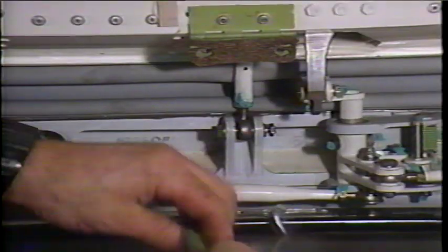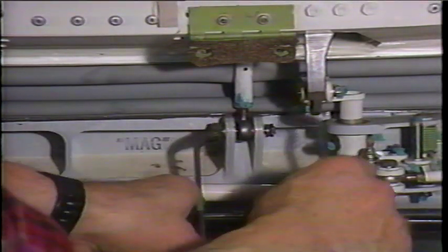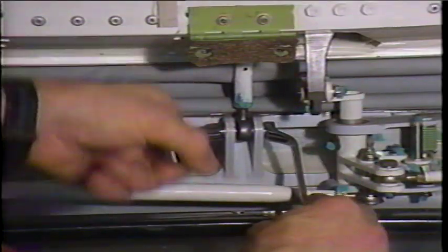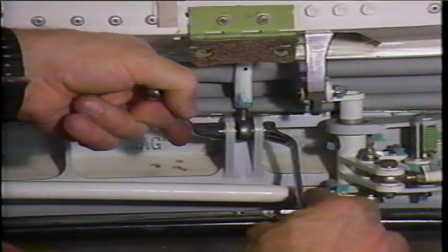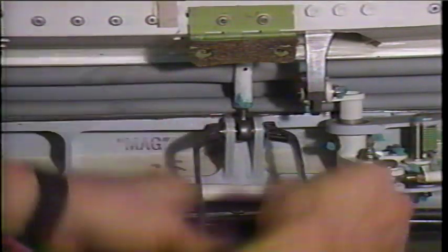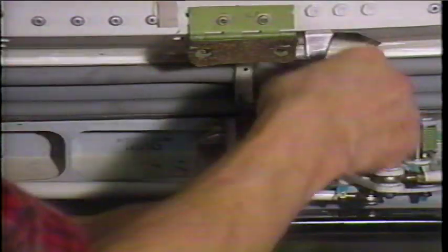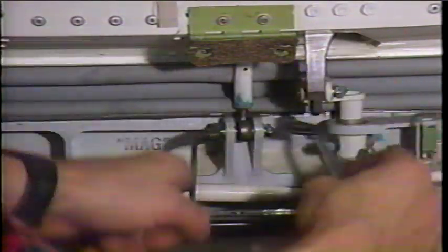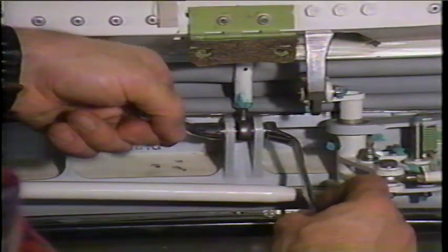The gate is in the proper position when the shim cannot be pulled out. Adjust the gate push rod as required in 1/2 turn increments. Install the bolt, washer, bushing, and nut to connect the push rod to the gate crank. Tighten to the recommended torque value. Tighten the jam nut on the adjustable rod. Repeat for the upper gate.